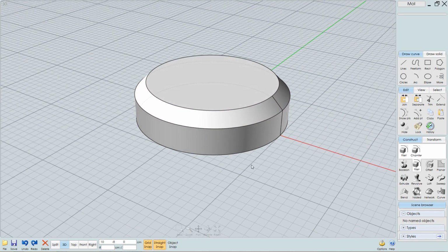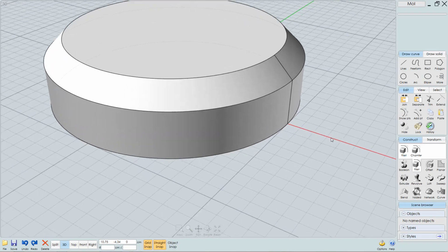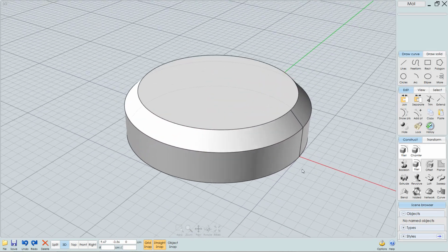And I'm not sure if I mentioned that before. If I didn't, I probably should. Like I said, you can move around the interface with these buttons down here, but I'm using the ones from Cinema 4D. So for me, pressing the Alt key, right-clicking and dragging means that I can zoom in and out.